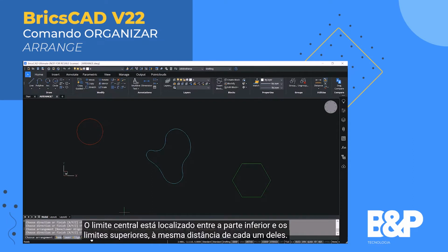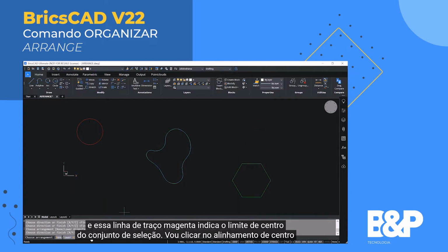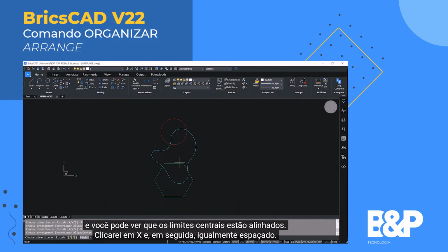The center bound is located between the lower and upper bounds at the same distance from each of them. In this illustration, the yellow dashed lines indicate the center bounds of individual entities, and this magenta dashed line indicates the center bound of the selection set. I'll click on center align, and you can see that the center bounds are aligned.